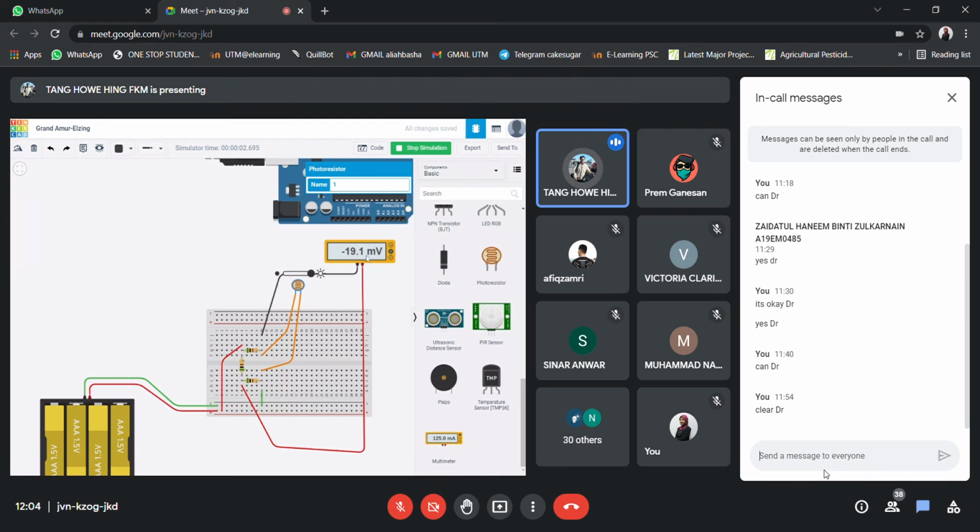It is not exactly 0 volt just simply because the resistors I'm using have some kind of inaccuracy or uncertainty, because supposedly I should use 506 ohm, right? So if I use 506 ohm, in simulation of course I can get these resistors, but in real life, I won't be able to get them.